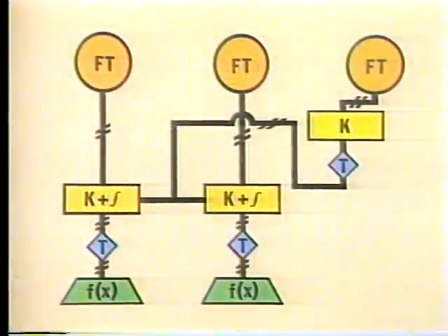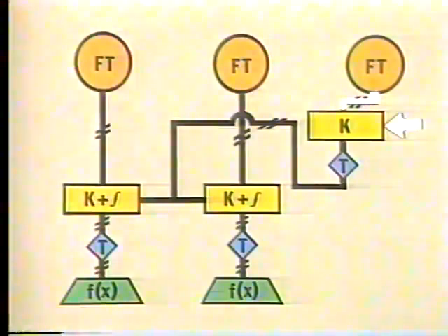To find out more about these instruments, let's see what this part of the control system looks like on a logic diagram. The steam flow transmitter is represented by this circle on the right. The output from the transmitter goes to the master controller. This symbol tells us that this is a proportional-only controller. The reason for having a proportional-only controller is that steam flow is not being controlled, but changes to meet plant demand. The only requirement for this controller is that it must produce a change in output signal that is proportional to the change in input.